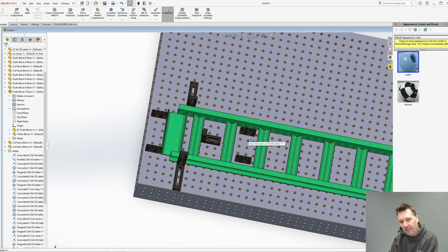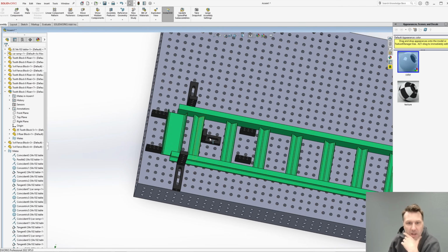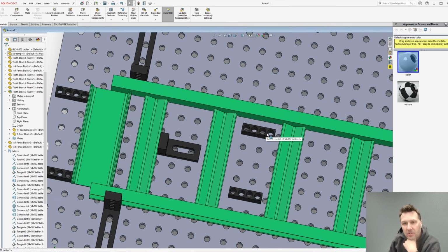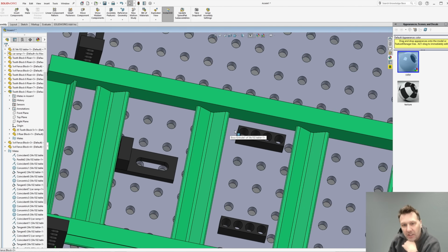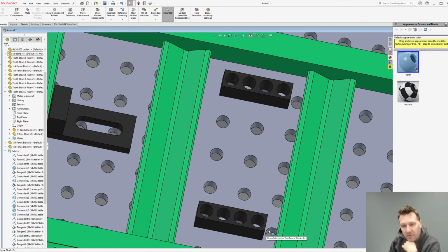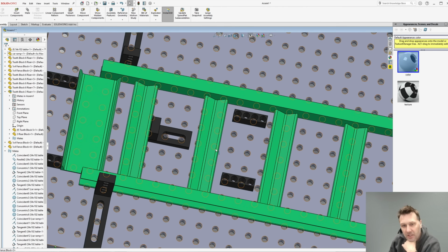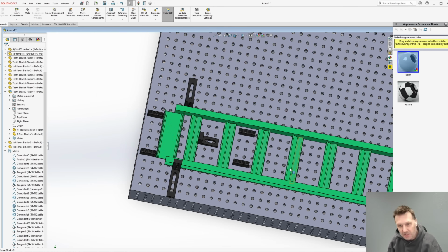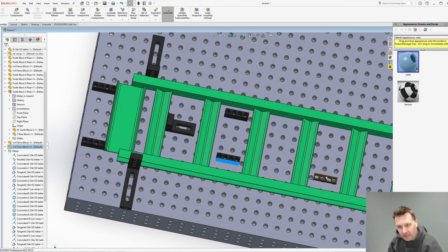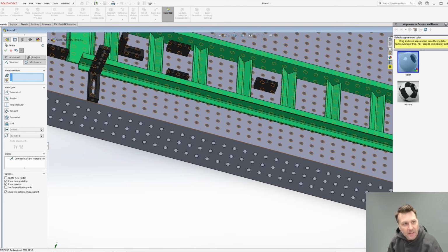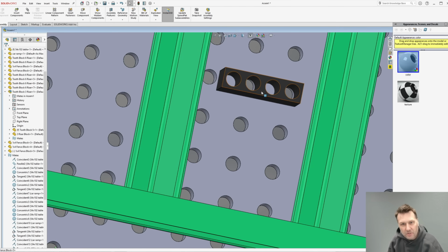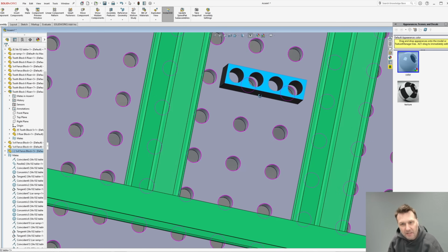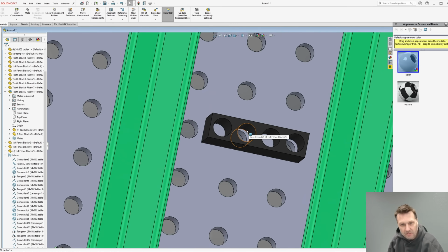And the neat thing about this one is you could probably get away with front and back. So you see how we have a block here, and then we also have a distance here and here. So we could shim off the front, shim off the back, and we could locate 2 at a time with 1 block. So the next block over, we could do the same thing like that, or you could just use 1 right here in the center. It won't really give you a squareness, but you could probably get pretty close with a square.